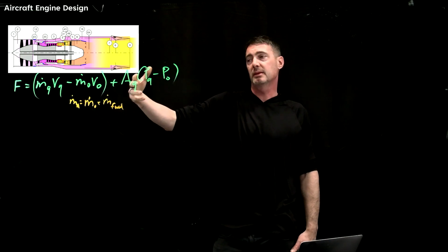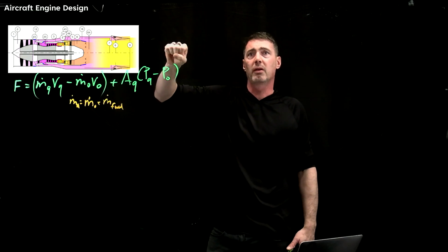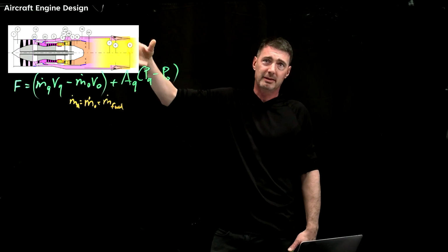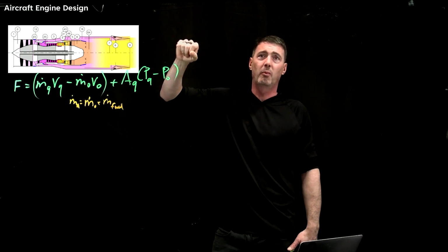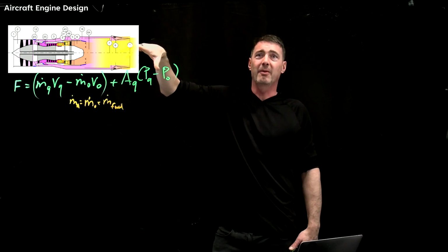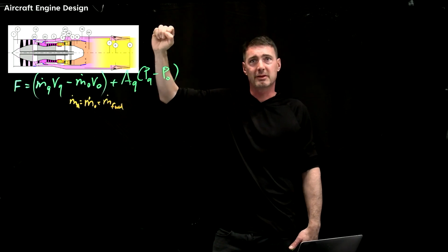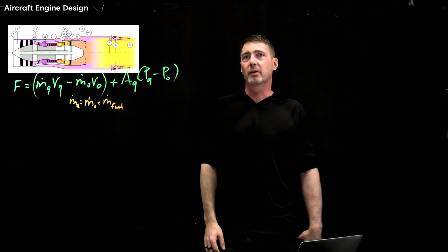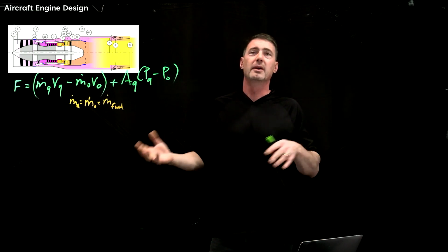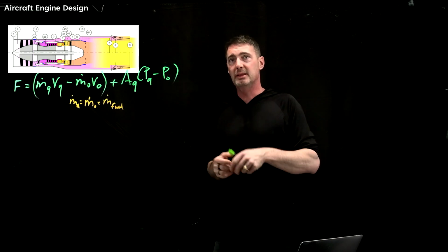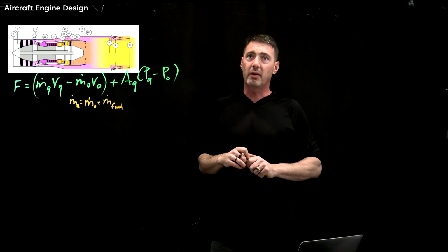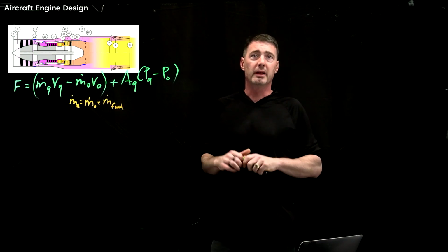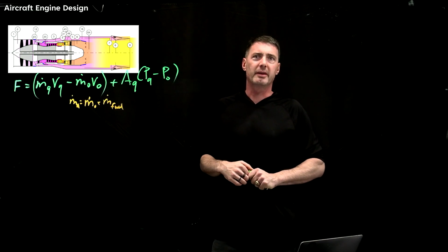And a lot of times, even from a thermodynamic point of view, you just consider all of this air, even though it's not. Even though this is now air and CO2 and water vapor. And nothing is ever perfect, so there's going to be some NOx in there. There's going to be some carbon monoxide in there. So a lot of this has flavors of: are you making an assumption, or are you trying to be detailed and accurate? It depends where you are in the design cycle. Sometimes you need to do both. Other times, it's a 1%, 3% correction you're not going to worry about.